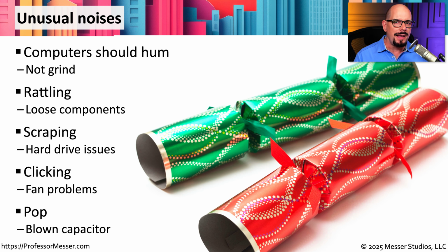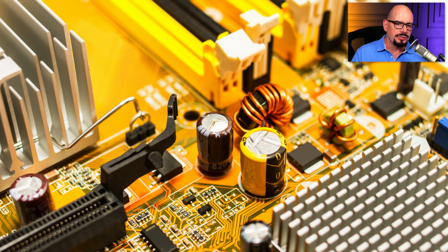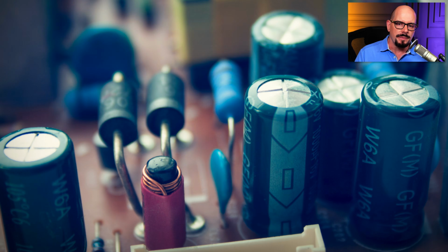And if you hear a popping noise and you see or smell smoke, your problem might be with a capacitor. The capacitors are located on the motherboard, and you may find that a capacitor looks fine with a flat top. There's no problems with this one, although right next door you can see there's a little bit of bulging on the top of that capacitor. Here's a view of some other capacitors. You can see the difference between a capacitor that may be flat on the top and one that might be bulging just a little bit.